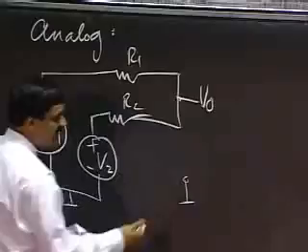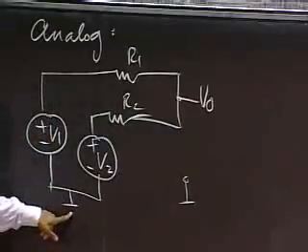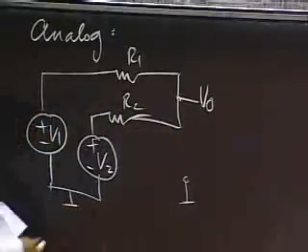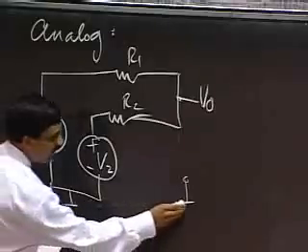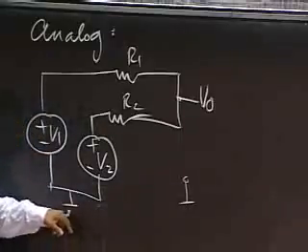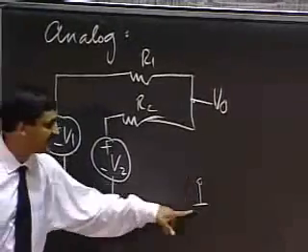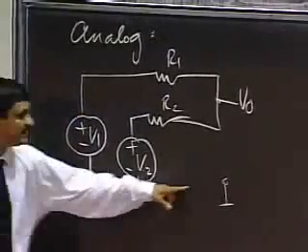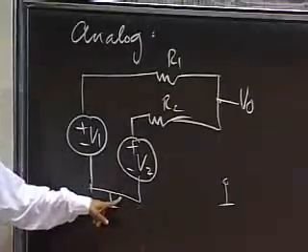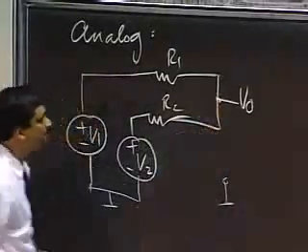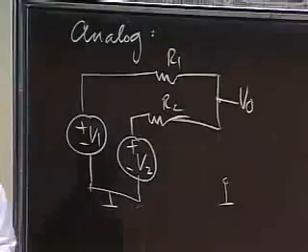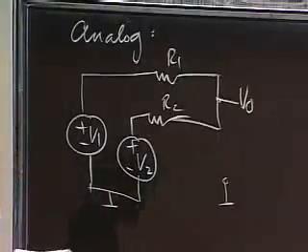This voltage is with respect to this ground node. Rather than drawing this wire here, I oftentimes draw a ground here and simply throw grounds wherever I want. This symbol simply refers to the fact that the other terminal is taken at the ground node. So here's my V0. Now let's go and analyze this and see what it gives us.